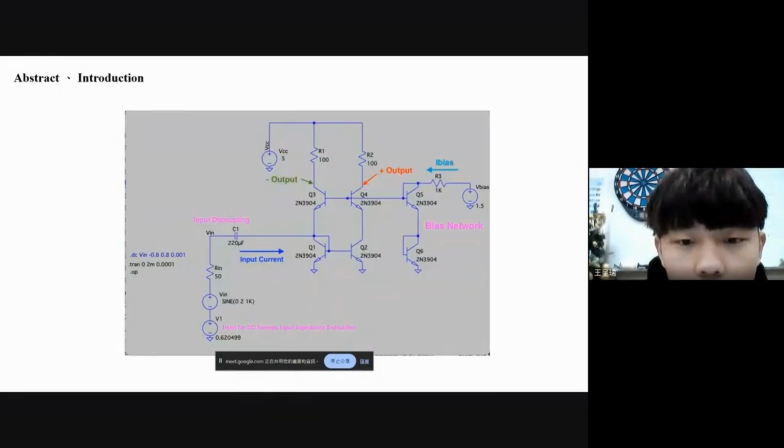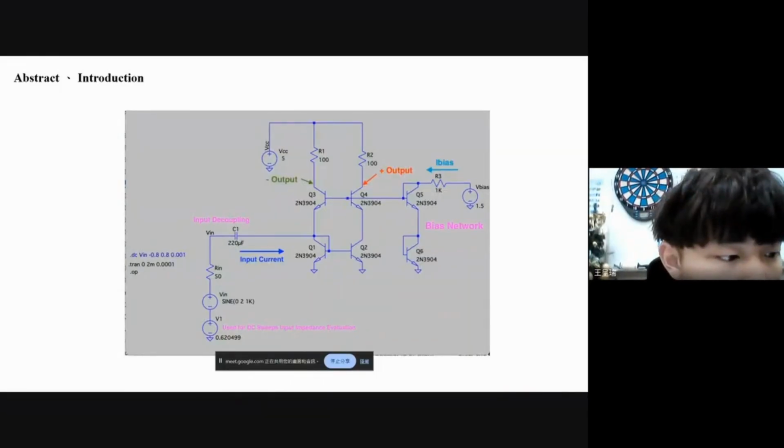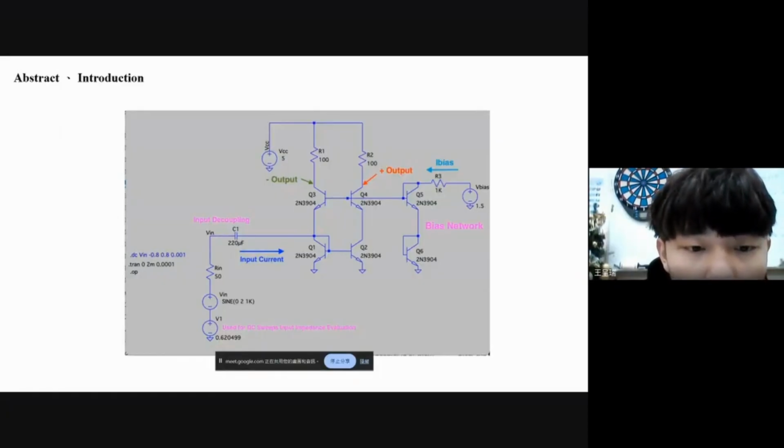First, this paper introduces an amplifier circuit derived from the Barrie Gilbert translinear topology. Its key feature is the ability to convert a single-ended input signal into a pseudo differential class AB current output under a single power supply.